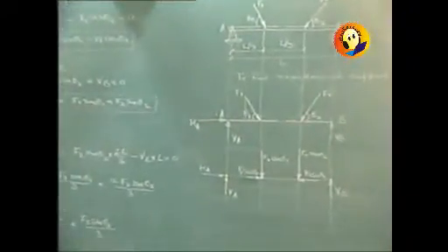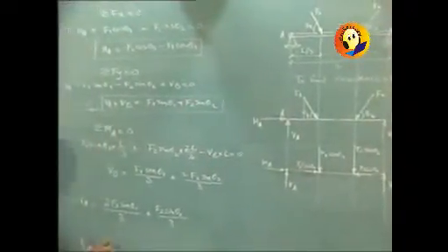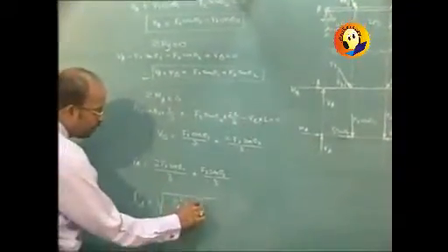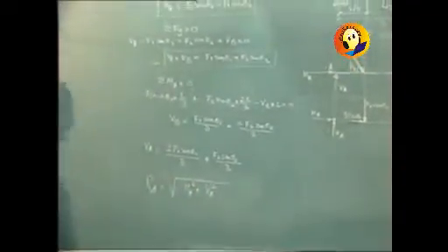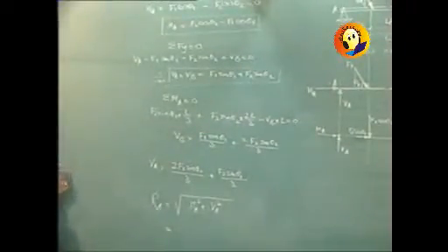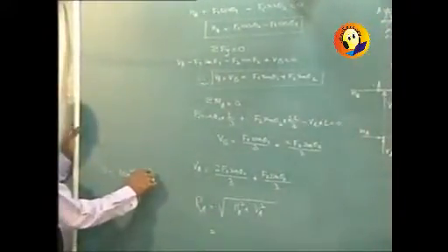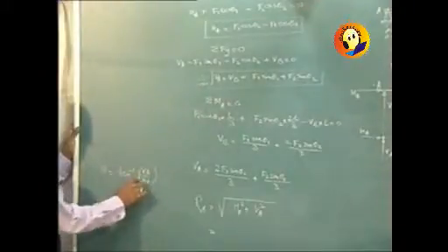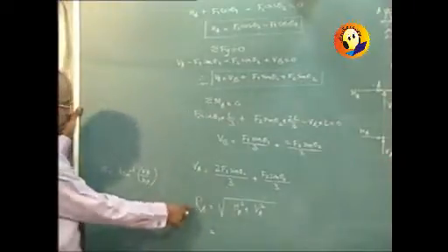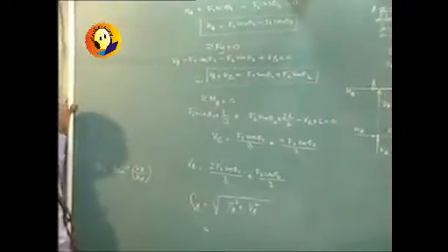Now at point A, if we are required to find the reaction at A, then we will have to use the same technique. We are required to square and add the horizontal and vertical reactions, and then even the angle made by that reaction can be calculated. It is going to be tan inverse of VA upon HA. And then the final reaction at A can be shown in the magnitude and angle format. Even an answer in terms of HA and VA is also a valid answer.